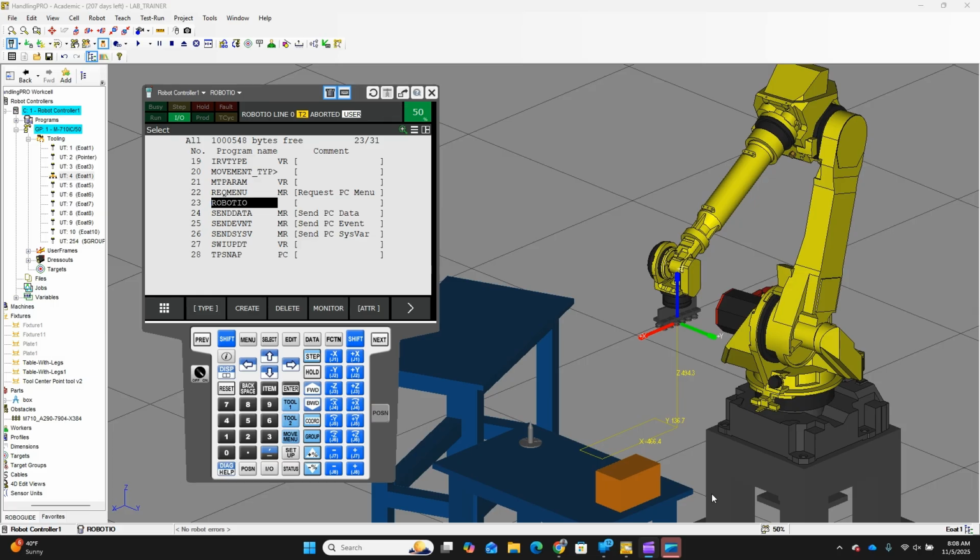So remember, in our shop, the robots do not have digital input and output capability. So we are utilizing the robot inputs and outputs as our connection functionality, where normally the robot IO is for things on the robot or end of arm tooling stuff. So first thing you need to know is how to get to it and what the robot IO is.